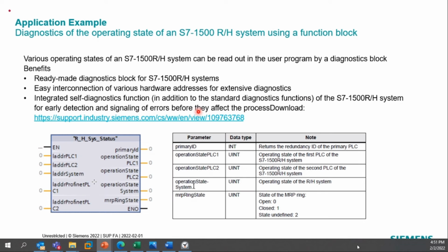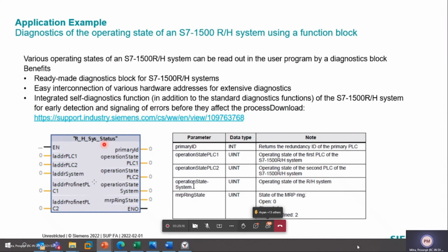Whatever the operating state of the CPU, if I want to show it in the HMI, whether it is running in run-solo mode, in sync-up mode, or which one is primary and which one is backup, all of this can be shown using this block. The block and application example are also available in the given link.